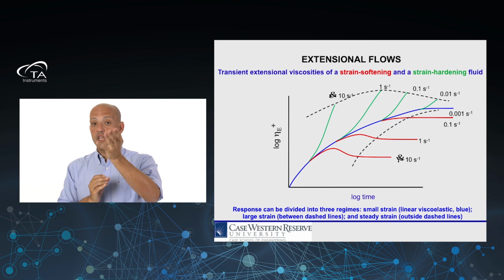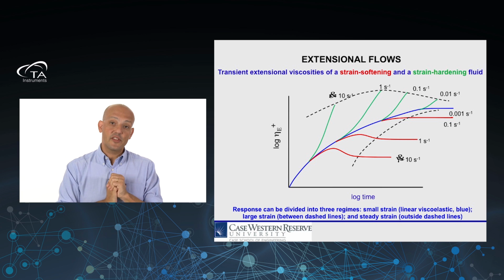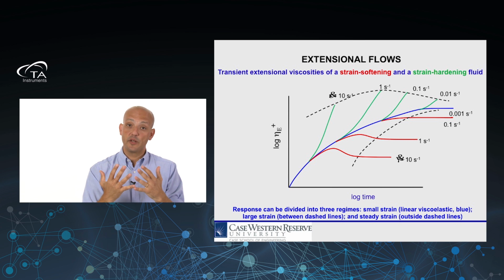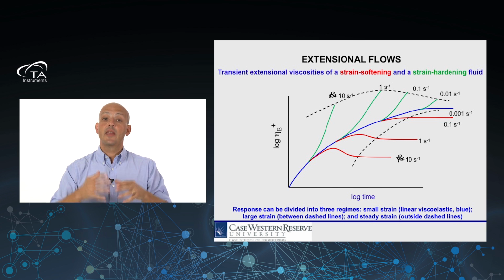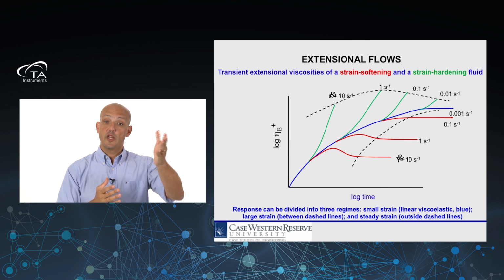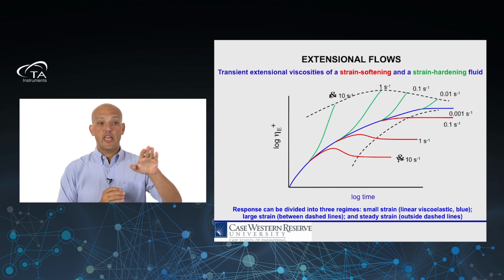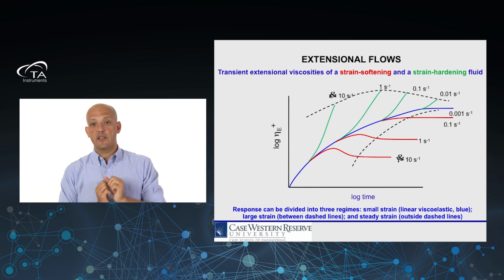Now, for example, in the case of this low-density polyethylene that we saw earlier, what happens is that because it's a highly branched material, the entanglement density is very high. It's a very elastic polymer, and that's why, for example, if we go back to that agricultural film line, that's why we use LDPE, because LDPE, being a very elastic material, can withstand large deformations. So what happens here is that as we increase the strain rate, we get the phenomenon shown there in green.